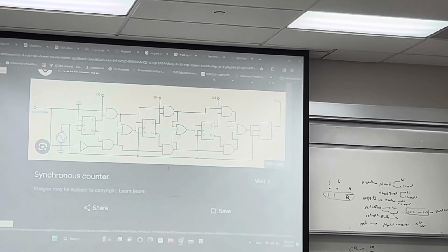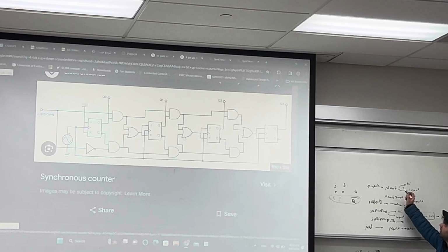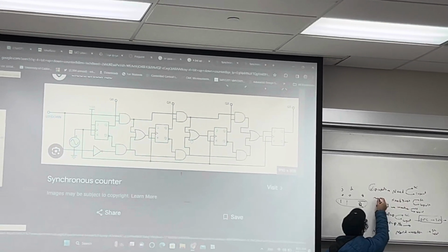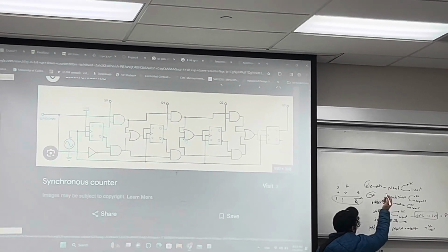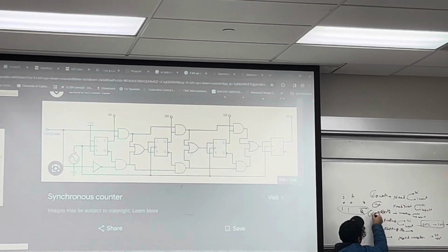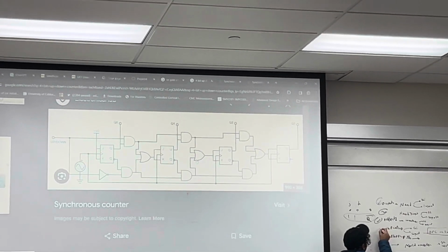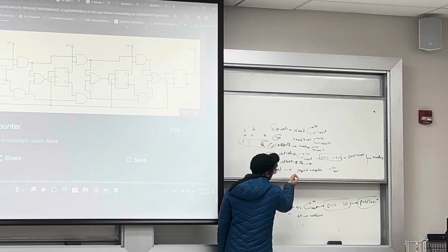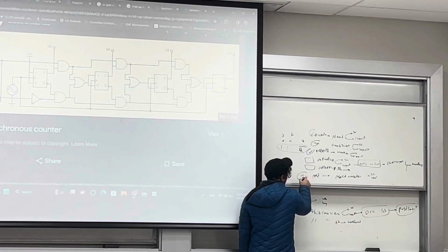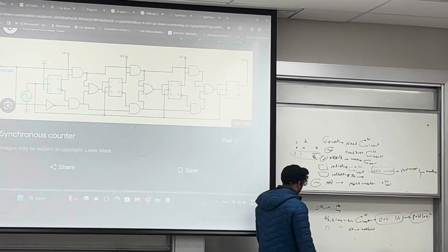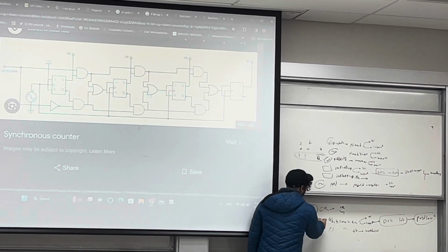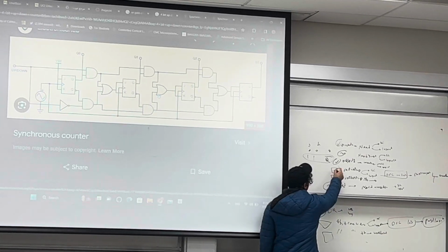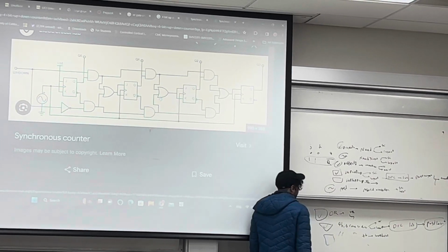So based on this design, the NAND gate, you have it right now. The NAND with 3 inputs is a little bit different. Add one transistor to this one, it's easy. Inverter, you have it. JK flip-flop, you need to design and test. And you have the NAND plus inverter, so it's easy. Again, you only need to put one inverter after the NAND. OR gate, you need to design, and also the 4-bit counter and 4-bit counter test bench. So 3 designs you need: JK flip-flop, OR, and 4-bit counter. 3 circuits.